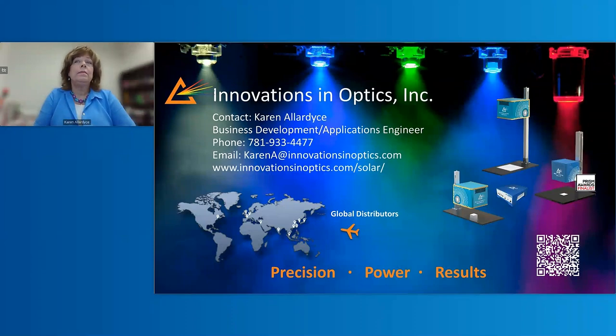This is important to advanced PV researchers using selective spectral illumination, for example, the blue only or the red only that I showed in the graph there, when you can dial it in on the GUI, or infrared only. Most solar simulators only specify uniformity for the combined broadband output. In addition, we calibrate uniformity wavelength by wavelength, not just with the full spectrum. So even with the full spectrum on, uniformity is better overall, because every wavelength meets the criteria.